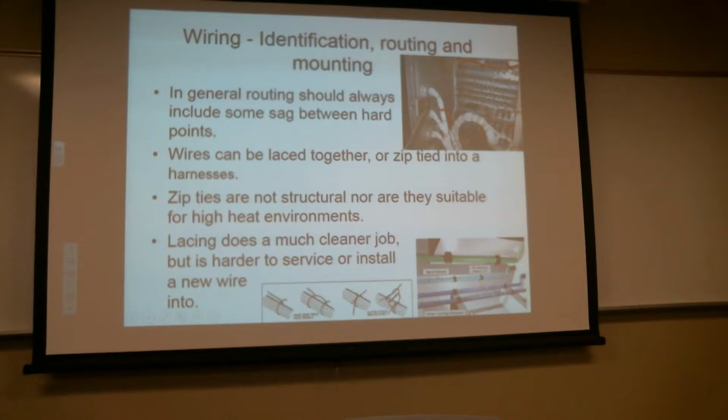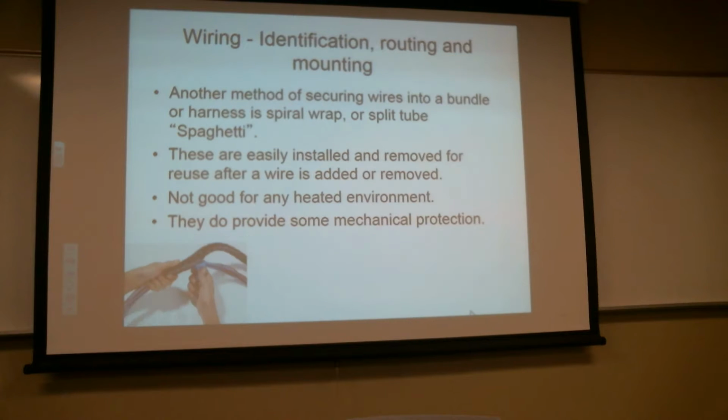So lacing, like I said, is also lighter, quite a bit less material. You're basically using the same thing that we use to rib stitch, and it doesn't weigh nearly as much as the zip ties do. Like I said, and again, nothing wrong with zip ties. There are many, many, many great uses for them. For many years, the FAA said they weren't going to say anything. They've now included it in several different places.